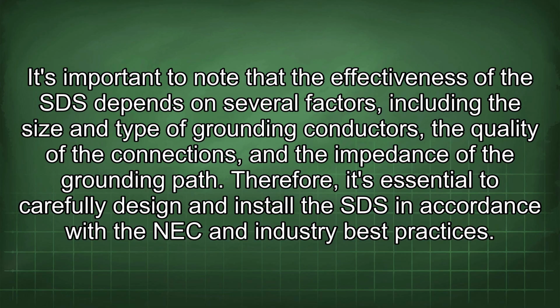It's important to note that the effectiveness of the SDS depends on several factors, including the size and type of grounding conductors, the quality of the connections, and the impedance of the grounding path. Therefore, it's essential to carefully design and install the SDS in accordance with the NEC and industry best practices.